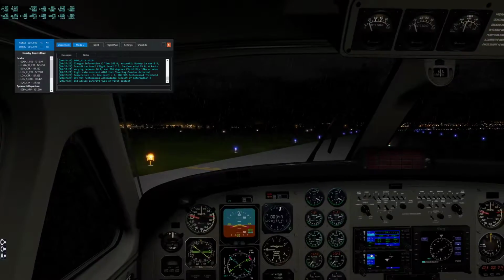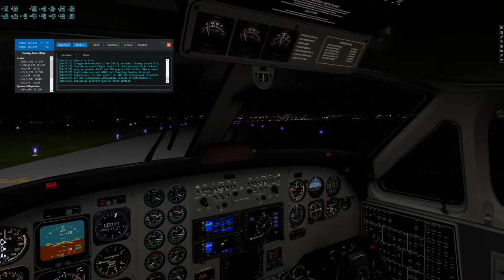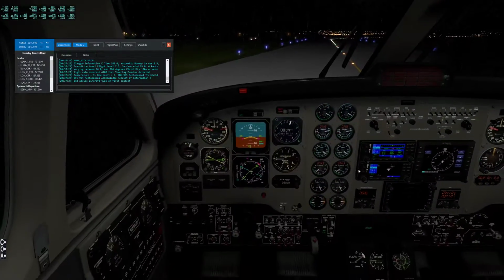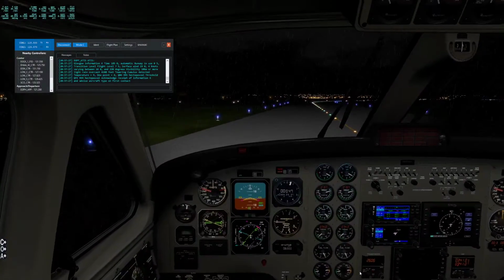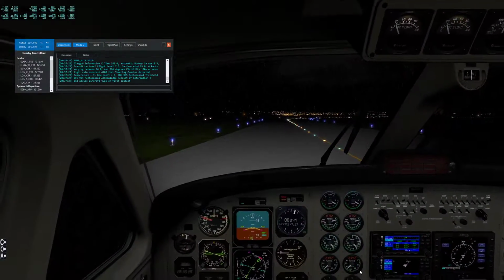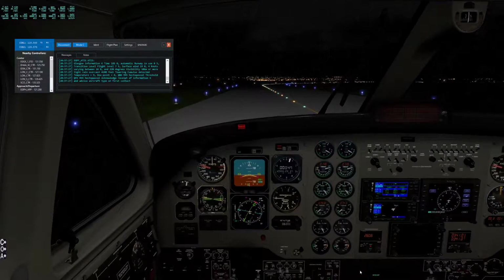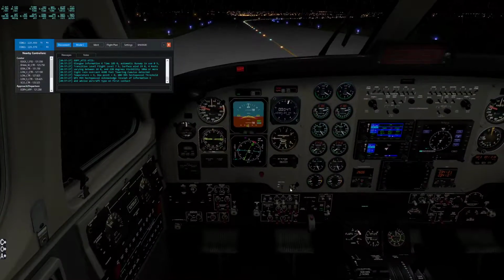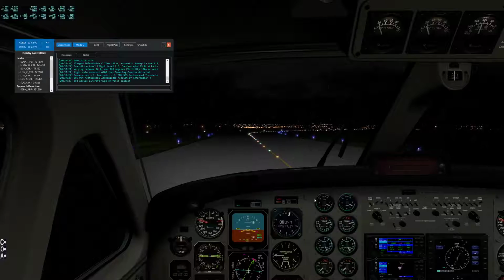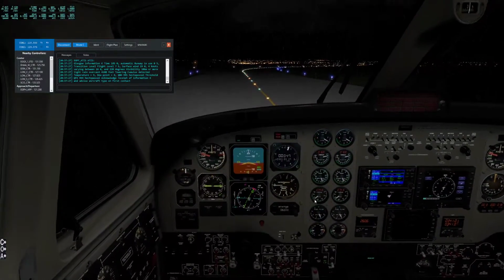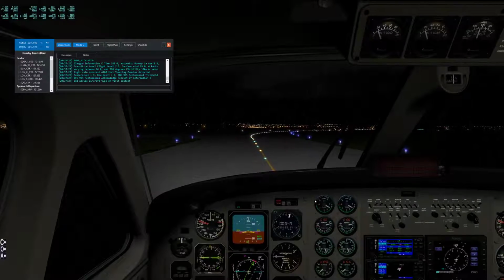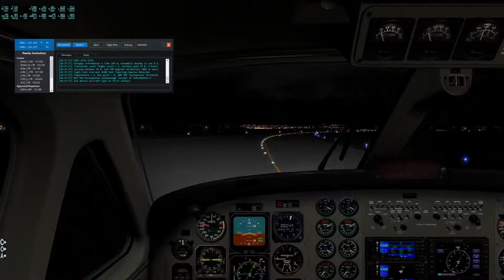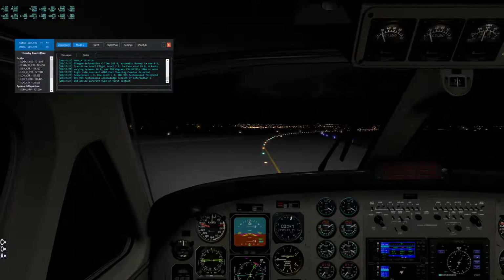I haven't actually turned the strobe on there, I don't think. I should also have set the transponder to mode C, altitude report, which I think I have done. I turn the strobe on now. Yeah, and I think I've already done the transponder. So strobes are on, landing lights on, transponders on, autoweather set, heading bug set. One notch of flaps in. No idea what the rotation speed is. What could possibly go wrong?